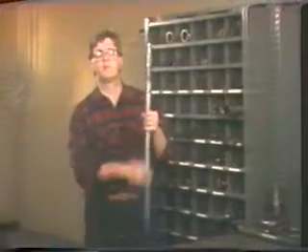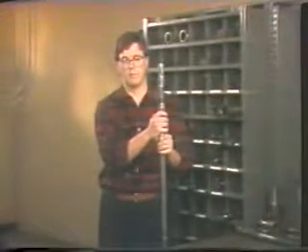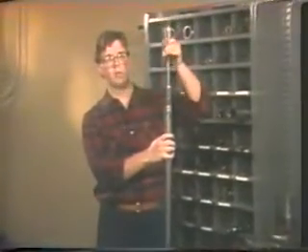Tubular jars, such as these here, are sometimes used in place of the link jars we saw earlier for some operations. They are made from a tube or cylinder which slides over a mandrel to deliver the jarring impact, like that. Hydraulic jars, or mechanical detent jars, such as these here, are used by the wireline specialist to deliver a harder jarring blow upward on stuck tools or subsurface controls than can be delivered with the mechanical jars.